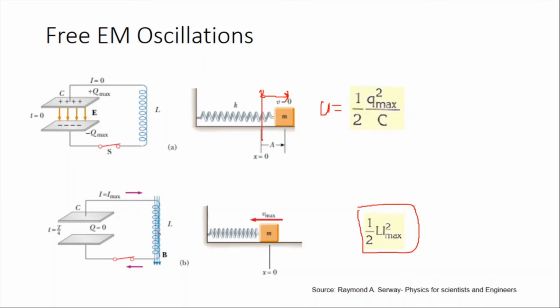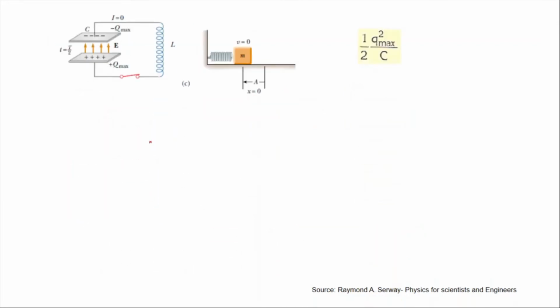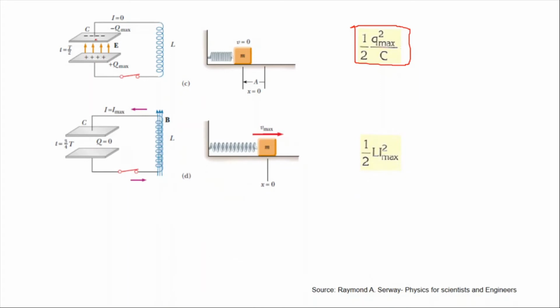The energy stored here is now going to be given back to the capacitor. Once more, the energy stored in the inductor will be transferred to the capacitor, and the capacitor is going to be fully charged. Again, this is the amount of energy on the capacitor, and in the analogy, the spring is compressed and there is potential energy stored in the spring. Then the current is going to move back through the circuit again. Once more, this capacitor is going to discharge, and all of the energy will be transferred to the inductor, stored as a magnetic field.